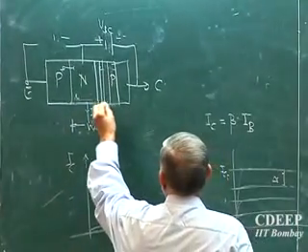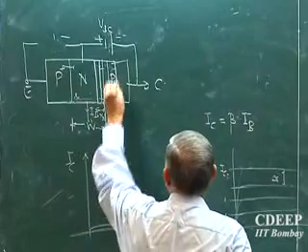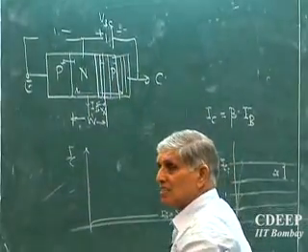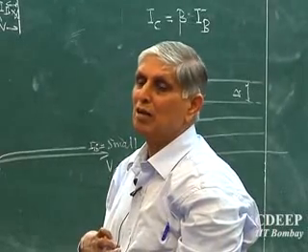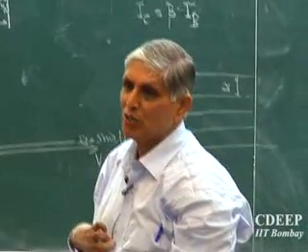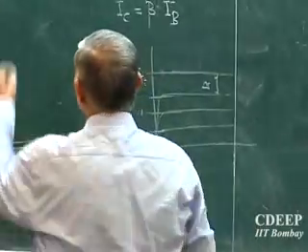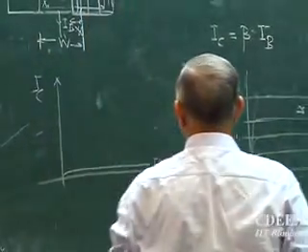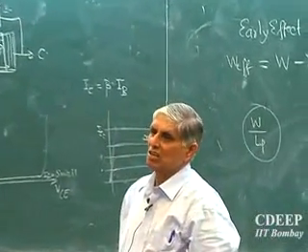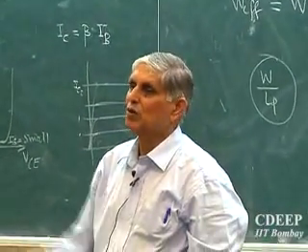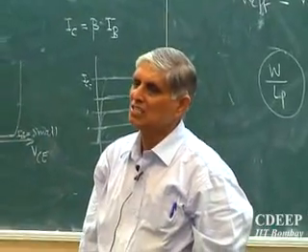However, this side is lighter and the depletion layer may start enhancing. Then at some voltage of VBC, it may punch through. So I may actually see a large collector current because the base collector junction is punched.